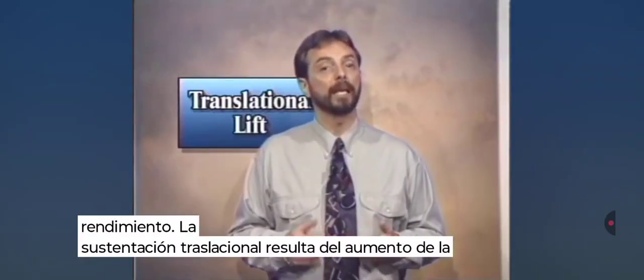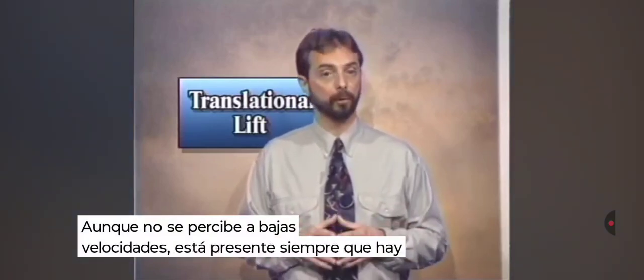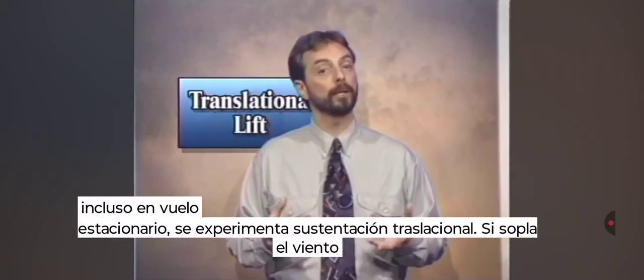Translational lift results from gaining airspeed, not ground speed. Although not noticeable at low air speeds, it's present any time there's movement of air across the rotor system. So even if you're in a stationary hover, you're in translational lift if the wind is blowing.